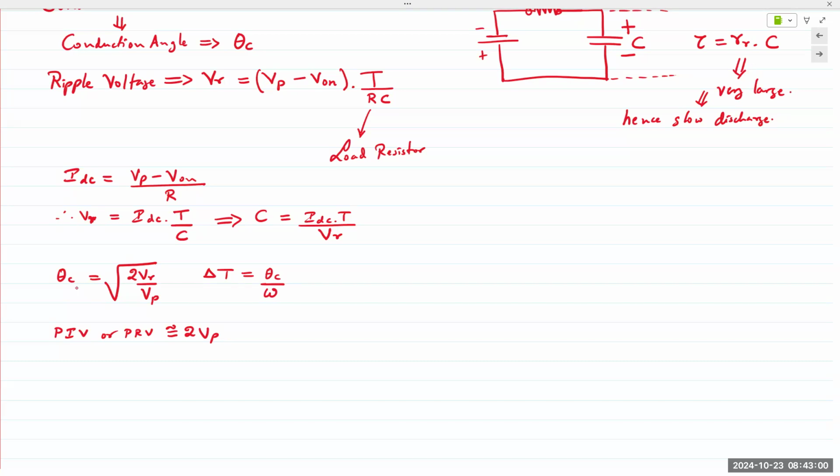Now, the filter capacitor we apply to the half-wave rectifier applies the same way to center tap, and the same way to full wave rectifier. We have a rectifier circuit, irrespective of whether it's half wave or full wave, we do have peaks, right? It's pulsating DC, or as I like to say, AC/DC. And so we have both AC as well as a pseudo DC in there.